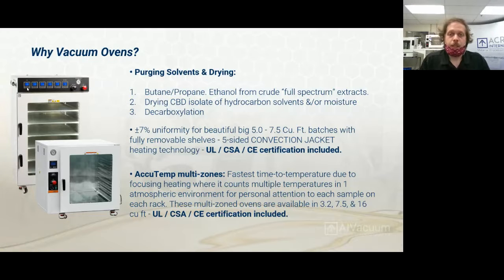but there's a lot of advantages as far as doing things at lower temperatures than you would be able to do under atmospheric conditions, and in general in a more sterile environment that doesn't have any atmospheric gases that'll degrade your material. And it's also safer because they're out of any ignition areas like in exposure of oxygen or any sparks. And so that being said, in the vacuum ovens and with vacuum, generally people don't put things that they want to heat on the walls.